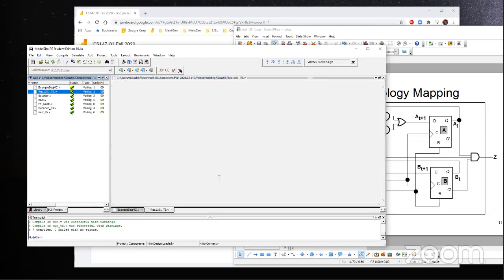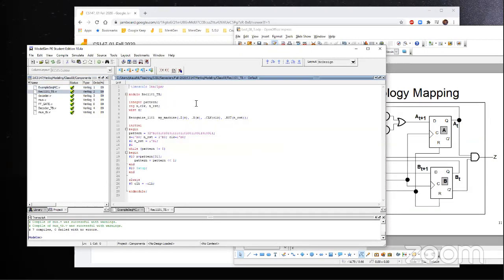Okay, now how does the test bench look like? Test bench is structure-wise simple. It has one register, a clock generator and a reset signal generator, or those registers, and an output for observation, Z. So Z is connected to the machine's output, X is connected to the machine's input, the machine's clock is connected to the CLK, and reset is N reset.